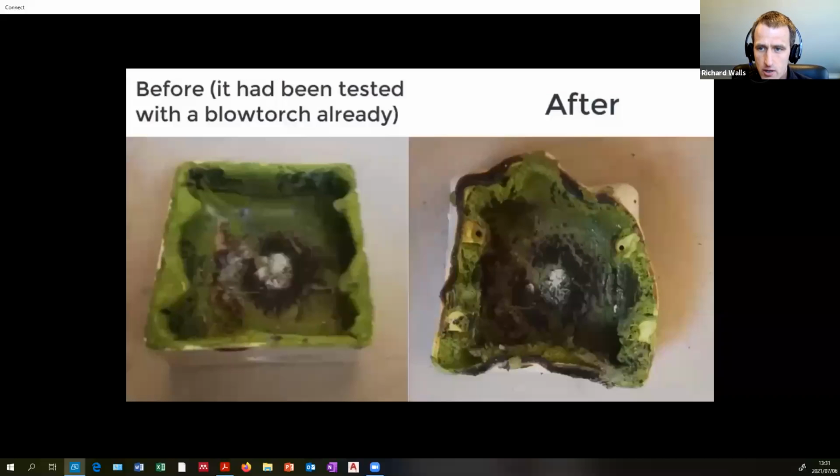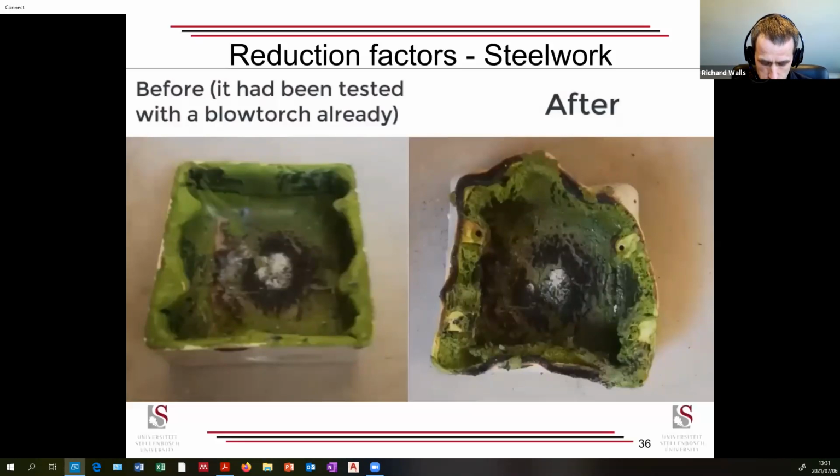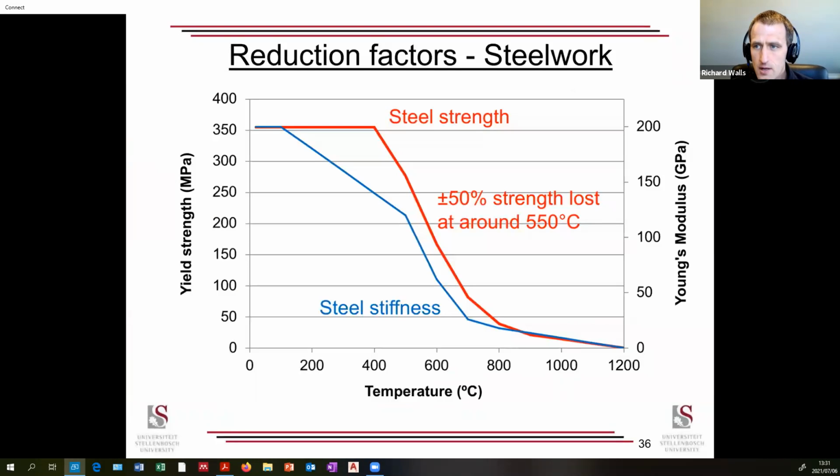So this is quite a cool way of protecting your penetrations, because as soon as you've got a penetration, you've got a weakening that the fire can pass through. But on this side, you'll see that the fire can go around it, so it just melts the plastic. Had the plastic been unexposed, it probably would have been fine, but the plastic was exposed here, so it got melted.